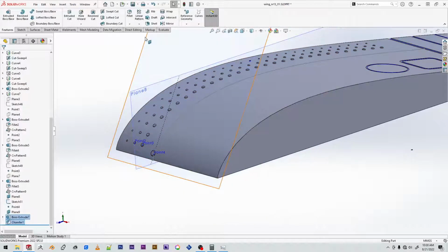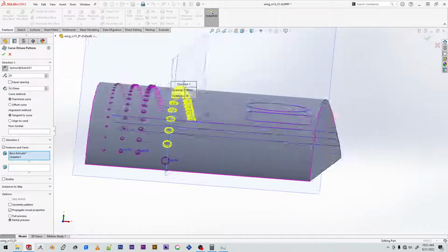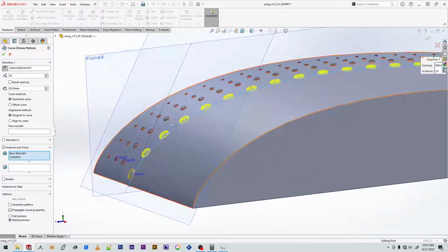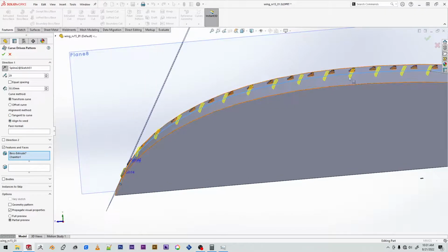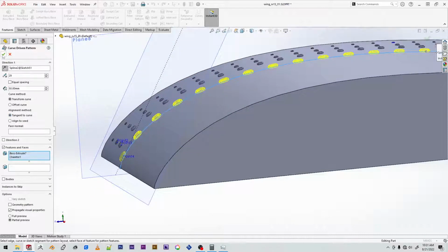Oops, I escaped. I'm so used to using my design software that I use escape all the time. All right. So we got that. Features tangent to. We want this tangent. If we don't do tangent to, this is what they'll look like. It'll keep the same angle. It basically aligns it to the seed. And we'll hit OK.